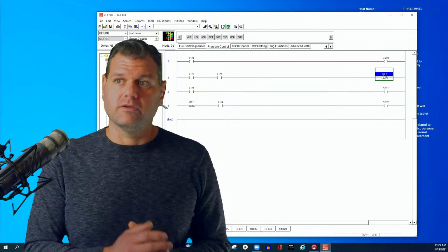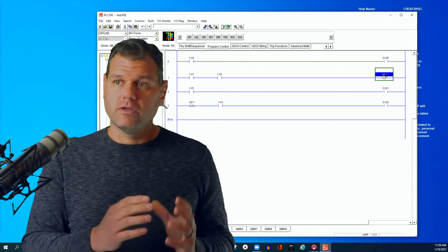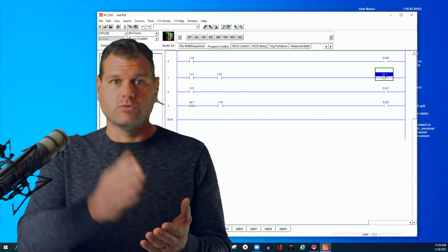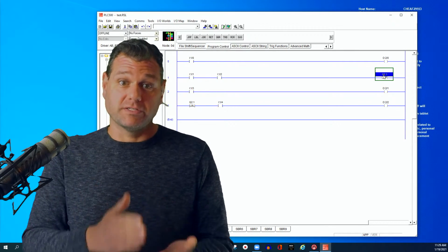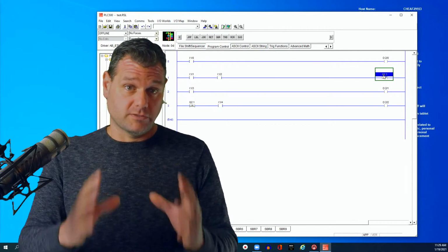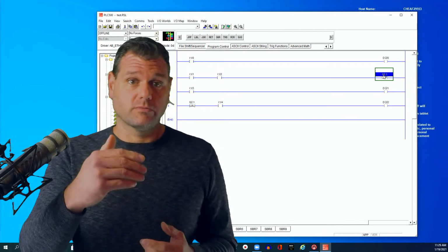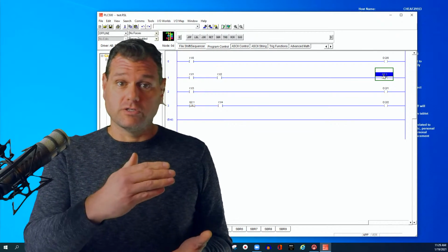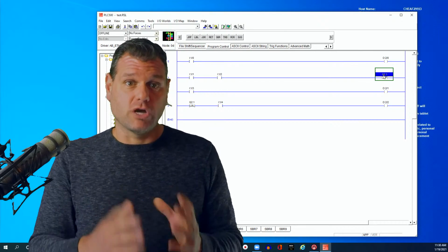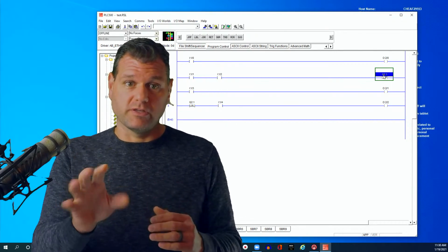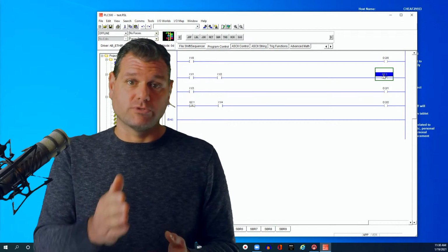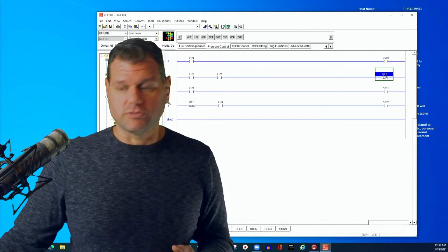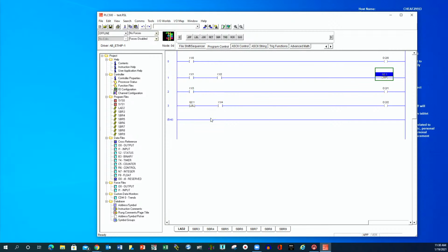So if you look at your stuff here, you're going to see that it has a Q2: and then a 1 or Q22 or whatever it is, right? The reason it's 2 is because we're in routine 2. If you want to jump to a subroutine, we'll talk about that later, you can say 3 or 4 or 5, whatever. It jumps to wherever you tell it, but this one lives on this guy. So Q21 is going to jump to another Q21 label, which you'll see at the bottom there on rung 3. So this will jump to here.